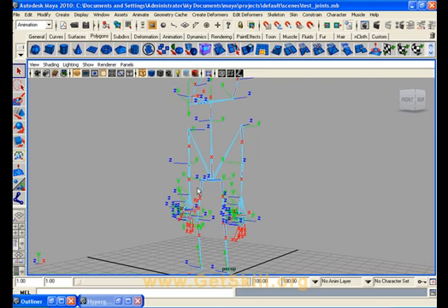It might seem confusing at the moment, but changing the local rotation axis is quite easy. There is one axis per joint, and if you dolly closer to a joint you will see that the axis respects the right hand rule, where the x-axis points towards the first child joint. As you have seen, in certain cases you will not want the automatic orientation setting.